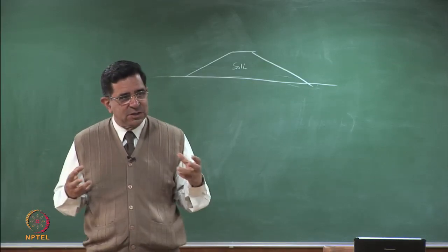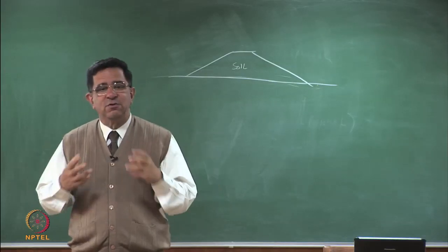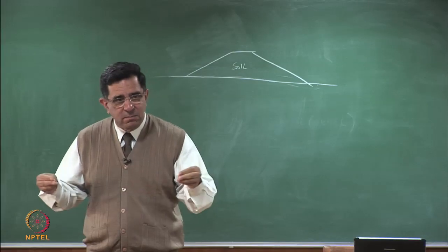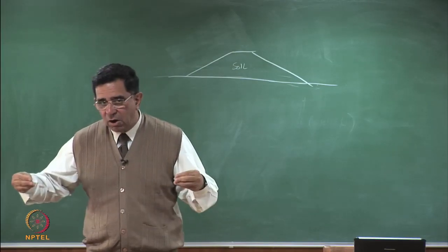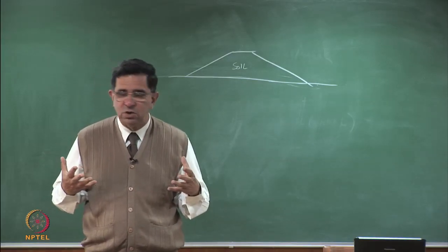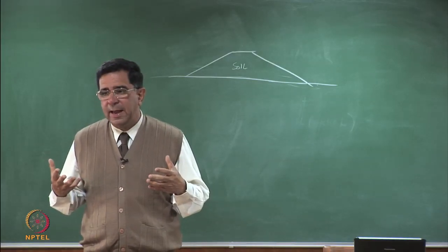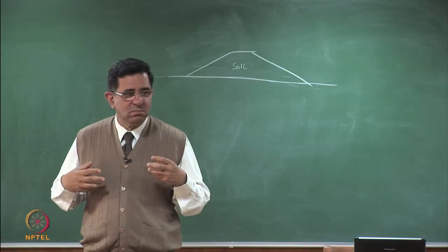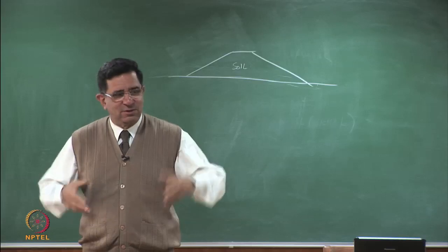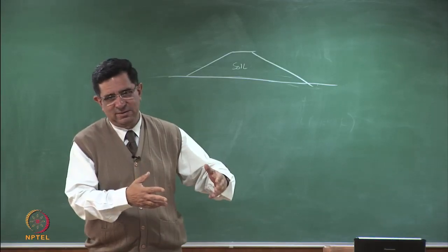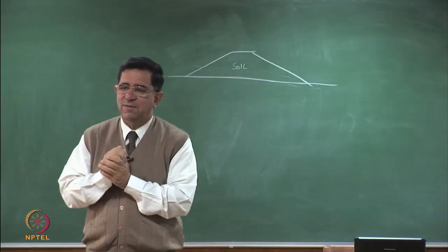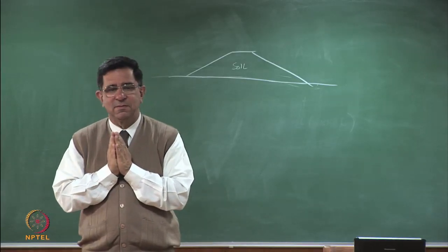So if you have fibrous material, they might give you some apparent cohesion. Now fibrous would be plastic sheets, small polythene bags, cloth. So you do get values of cohesion intercept. And so you get C dash, phi dash. So C dash can be more than 0 for waste. What kind of phi dash would you expect?